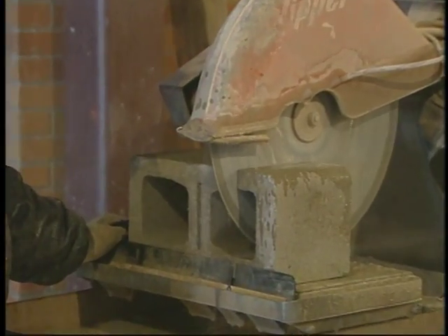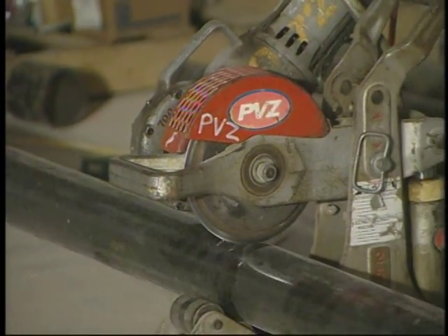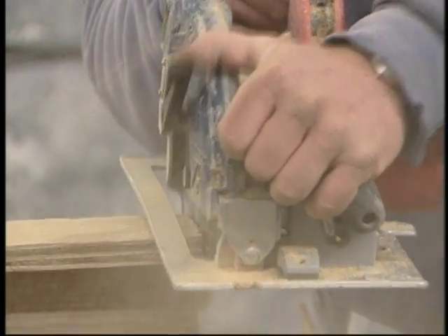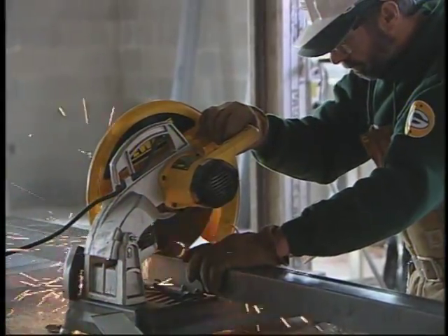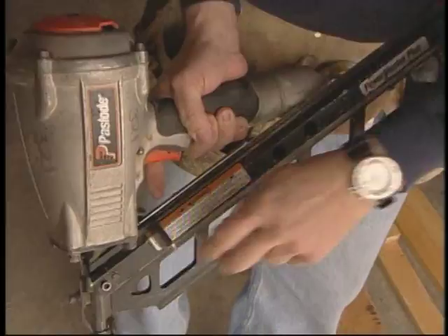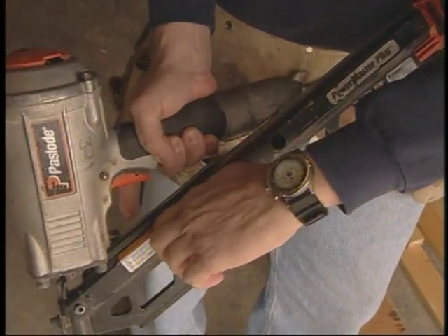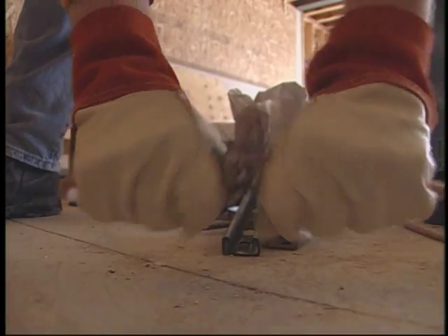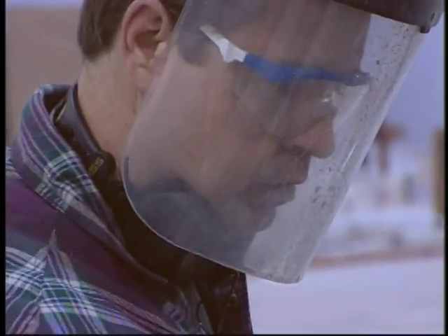If power tools are designed to have guards, they must be equipped with those guards when you use them. Guards protect you from getting your fingers, hair, or clothing caught in moving parts. They also help protect you and your coworkers from flying chips and sparks. Don't remove a guard just because you think it's in the way. If guards are defective or missing, the equipment must be taken out of service. Always disconnect tools when not in use, before servicing, and when you're changing accessories, such as blades, bits, and cutters.